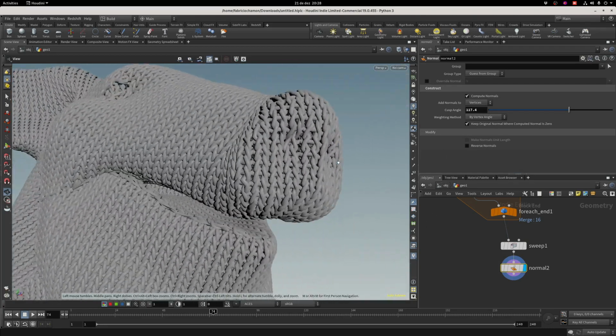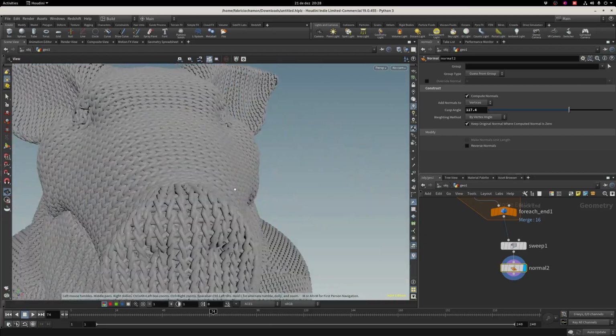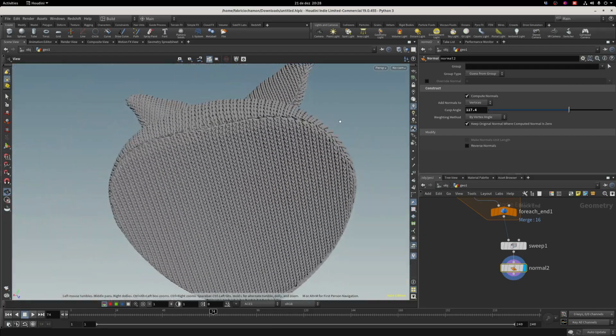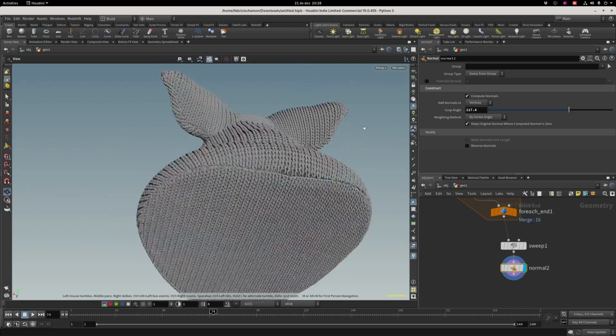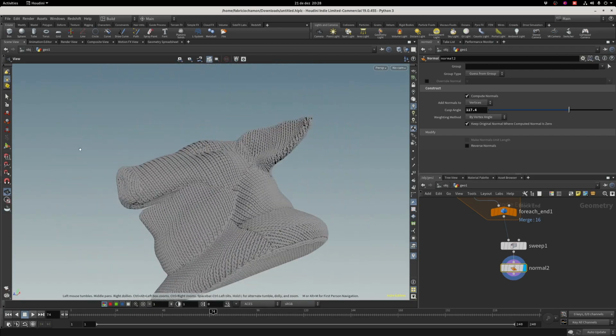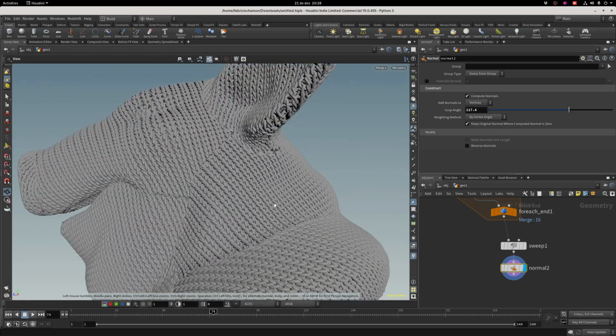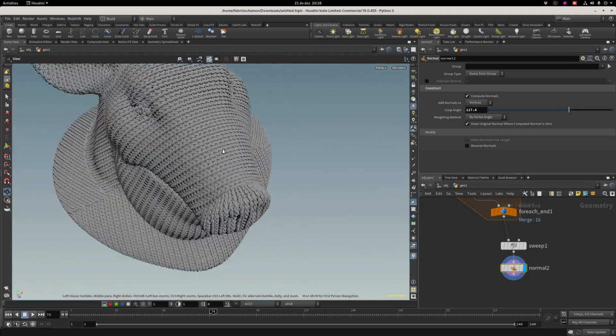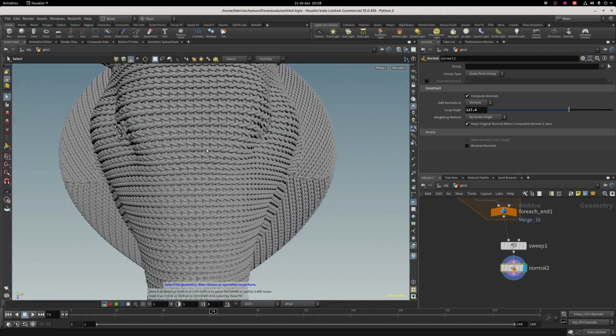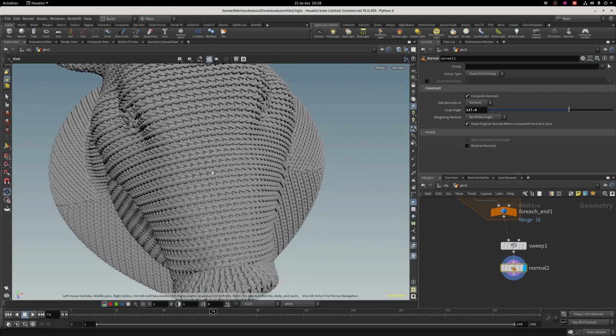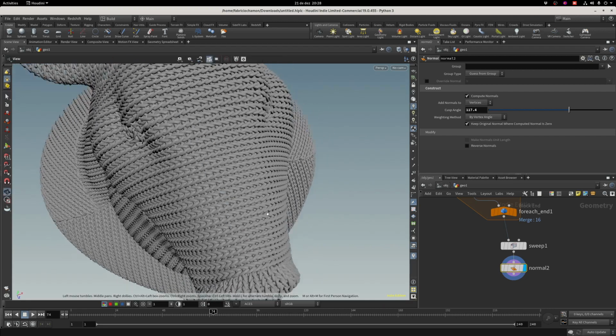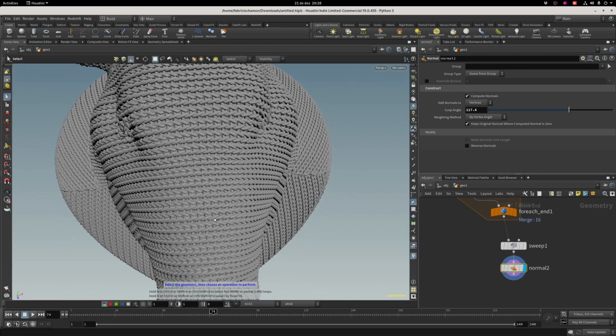interesting geometry for knitting. And now, for example, the UV shells, like the rotation, they play a big role in defining the pattern direction. For example, if you want this area on the head to run downwards here, you can always go back and rotate the UV island on that piece, and that's going to make the threads run downwards.